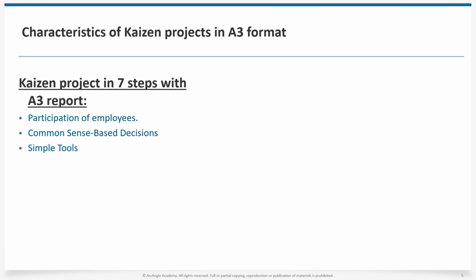Kaizen projects often include initiatives for workplace organization, known as 5S: sort, set in order, shine, standardize, sustain, and implementing mistake-proofing techniques. These efforts aim to enhance workplace efficiency, cleanliness, and standardization. Kaizen projects require management commitment to make prompt decisions on team recommendations. The decision-making process involves a yes/no/to be further explored approach, ensuring timely progress and swift action.